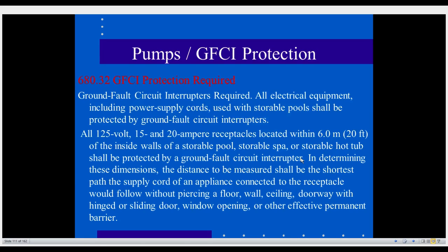So any receptacle, no matter where you place this storable pool, if I have a receptacle that is anywhere within 20 feet of this pool, then we're going to have a requirement to have the GFCI protection. I think you're going to get that anyway, just like what you had with a permanently installed pool, but it's just kind of echoing that here with a storable. Okay, so it kind of matches the same requirements as a permanently installed pool in that aspect.